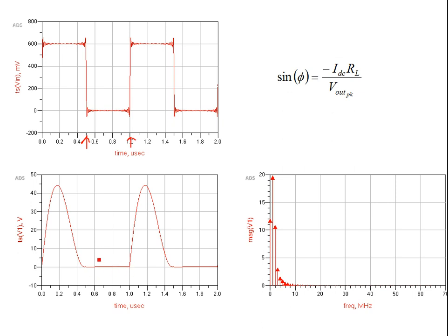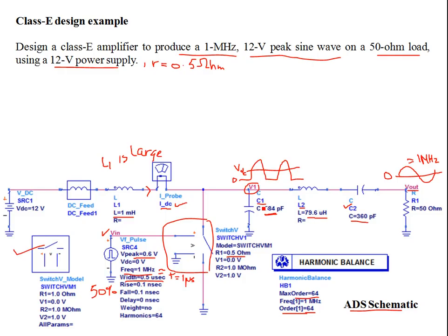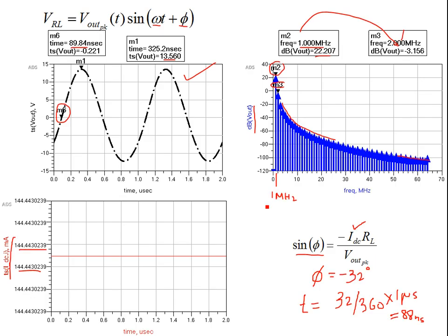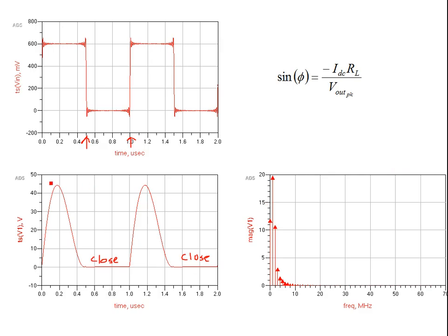Switch closed means the transistor is conducting. We have a voltage controlled switch, and when it is closed, V1 is shorted out due to a very small resistance R that was 0.5 ohms. It was a short circuit. So in these regions we assume negligible current flows through C1. Instead, all the short circuit current flows from here, so nothing goes here. Over here, the switch is open.